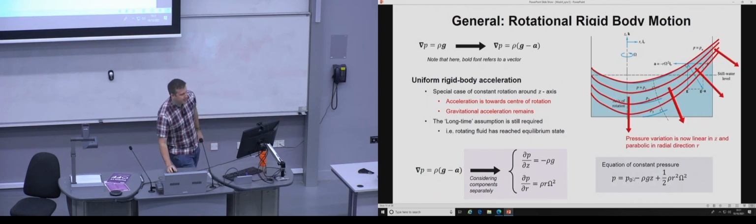And this expression is telling us basically that the sum of these two pressure gradients result in the overall change of the pressure. So there is a pressure change due to the change in z and a pressure change due to the change in r. So versus this axis, if you go this way, in the radial direction, you're going to increase this term. r is going to be non-zero because at the axis r is 0.